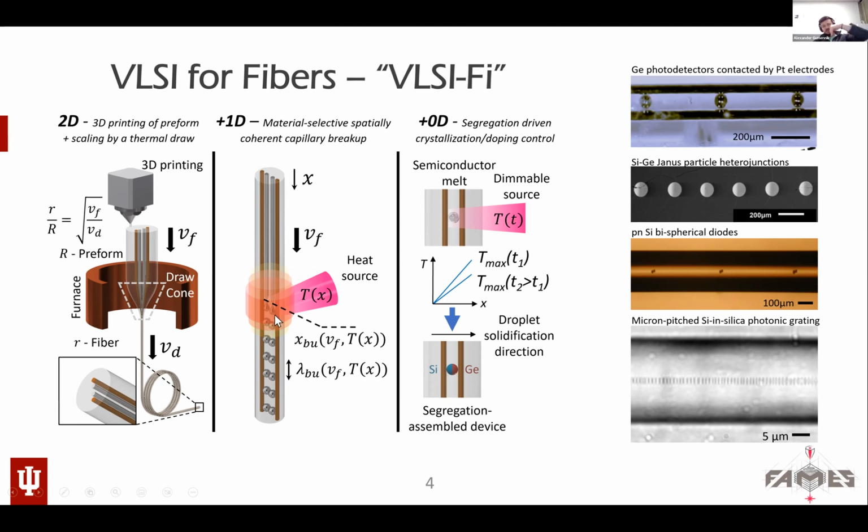Okay, and what you will observe is a capillary breakup that is very similar to how water drips from a faucet. It will have droplet by droplet liquid core forming at the tip of the continuous section of a core and detaching, and you will end up with a periodic structure of bispherical entities. So sphere that detaches from a core that is broken up by the capillary breakup process is always larger than the diameter of the initial core, because it collects material from certain lengths of a breakup period.